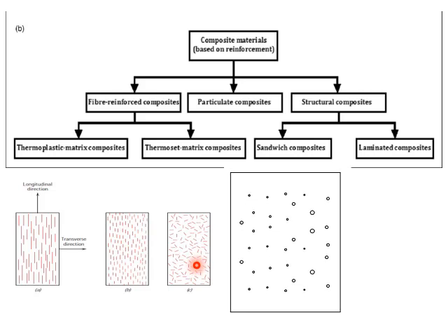If it is a particulate composite, we are going to have an L by D ratio, that is the length to the diameter, that is less, where the diameter is more and length is less. Okay, so this is exactly what we get in a particulate composite. It is similar to the solid solution strengthening we discussed in the strengthening mechanism for metals, where we have secondary hard particles which act as an obstacle to the movement of dislocations. But here not exactly dislocations, they will hinder the movement or the deformation of the matrix material, by acting as an obstacle and giving strength to the composite material.